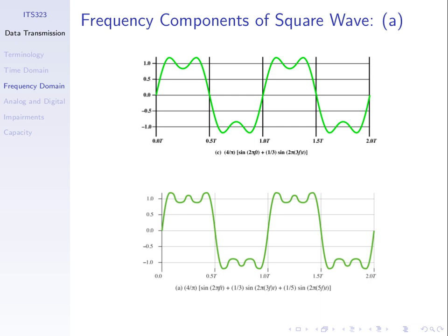What's its bandwidth? What's the bandwidth of our signal? The absolute bandwidth in this case. 2,000. Where do you get 2,000 from? The maximum frequency component minus the minimum.